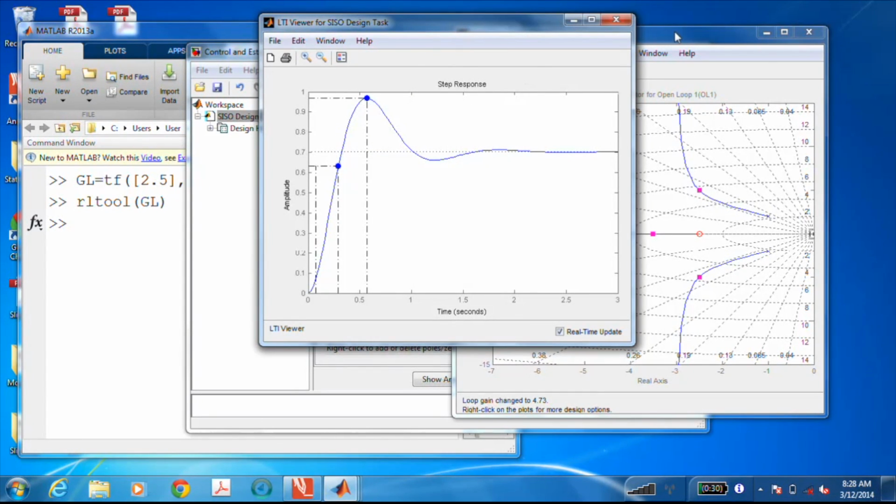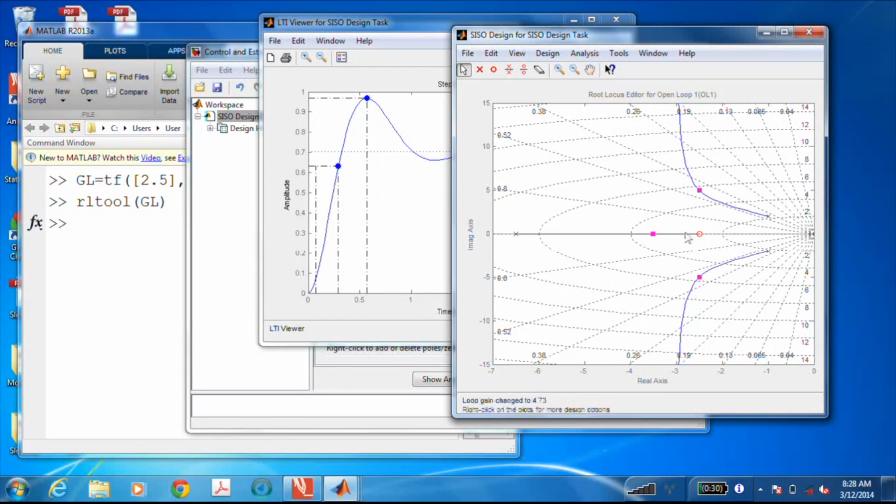And the reason for that is that our closed loop poles, this complex pair, is no longer actually dominant compared to the other complex pole, which is right here. So if we really had to get the lower percent overshoot, we'd have to adjust our design a bit so that our damping ratio is more aggressive than the 0.44 or so that we have right now. We can see that by clicking on the pink line, and we can see that the damping ratio is about 0.45 actually.